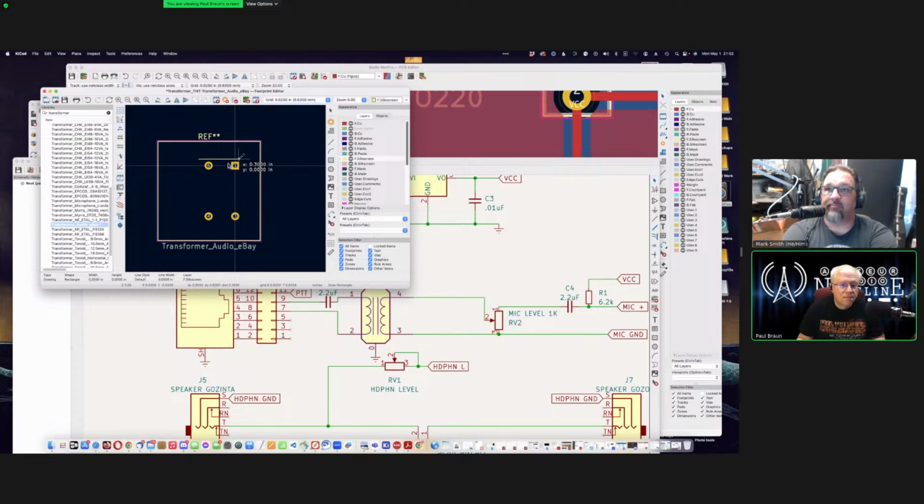So you are drawing a box now. So you're not doing, move here's down and you'll see the box expand out. Oh, yeah. Okay, cool. So 0.5 tall and 0.6 wide. So go ahead and go all the way out to 0.6. And then you can drag it and center it over those pins.